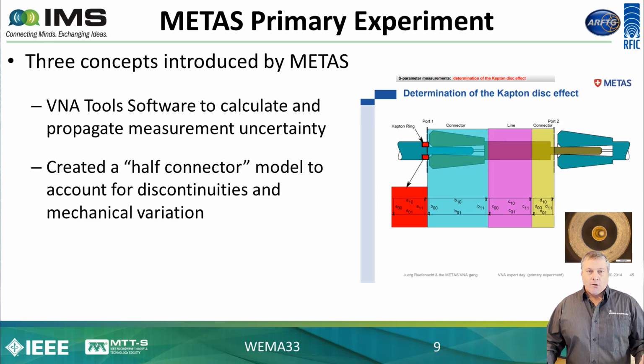So you have a mated connector pair, a male-female connected pair that's mated. They split that connector pair in half, I believe, at the calibration plane, and they spend a lot of time modeling the imperfections of these mated half connectors with the goal of being able to reduce uncertainty in that mated connector pair. So what can be done to make the connector pair more repeatable and more traceable, and also with the goal of de-embedding the imperfections of the connector pair. So I think a lot of work has been done in this area to improve the uncertainty contribution of the mated connector pair, to understand what's contributing and then remove that from the overall measurement uncertainty chain.